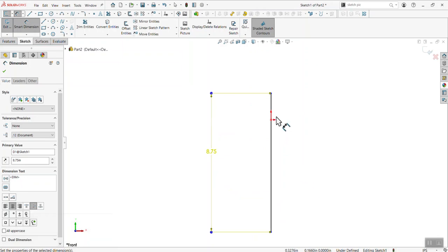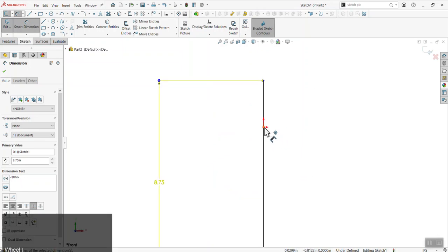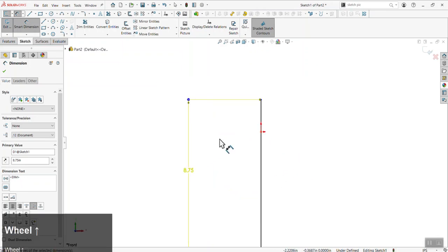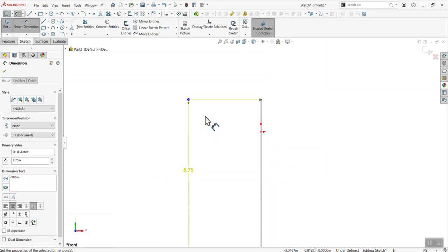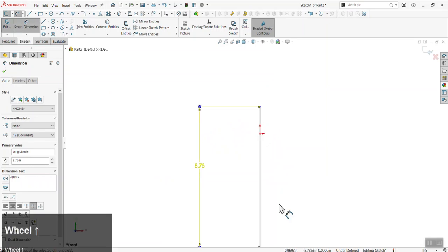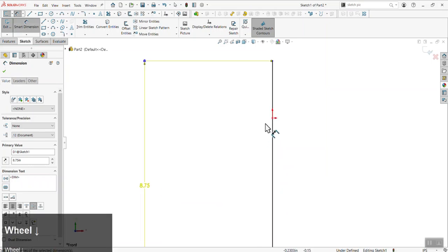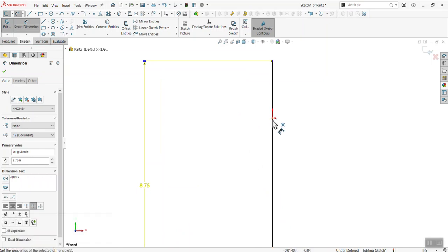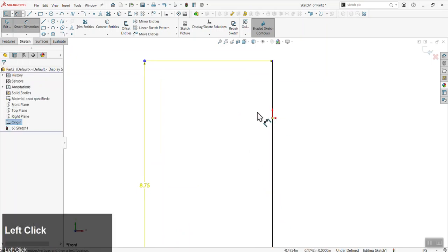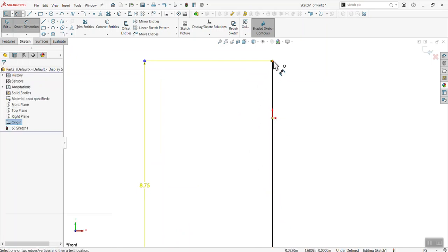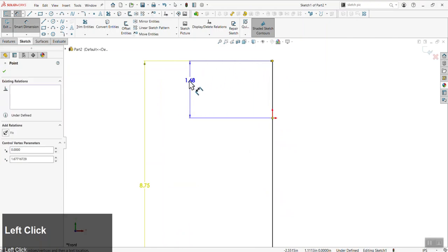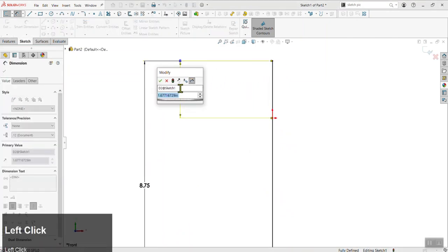It doesn't look like anything changed, but the scale has now been set, the proportion has been set to this line. The next thing I want to do is set the height of the cap from the origin. I still have the dimension tool. I know that because of the icon near my cursor, and I can also see here it still says dimension and it's depressed here. Now instead of clicking the entire line, I'm going to set a dimension from 2 points. So I'm going to hover over the origin, it turns orange. I'm going to click on that, and hover over this endpoint and click on that, and drag the dimension off to the side.